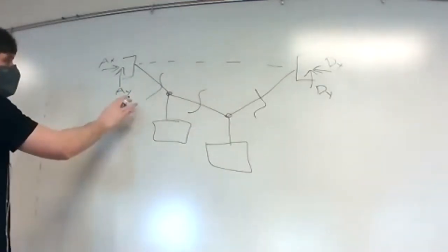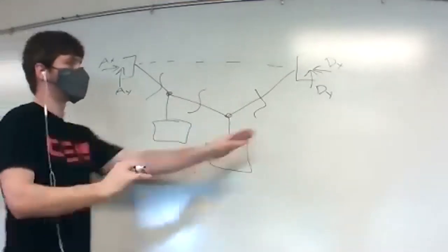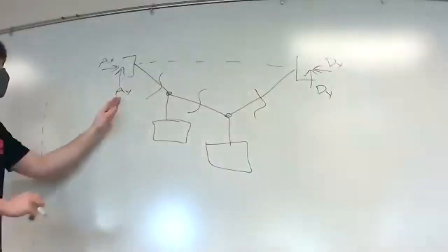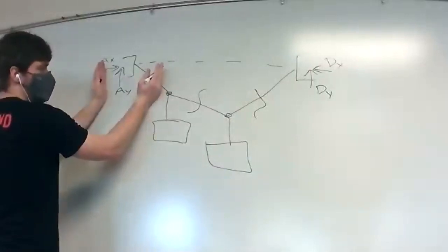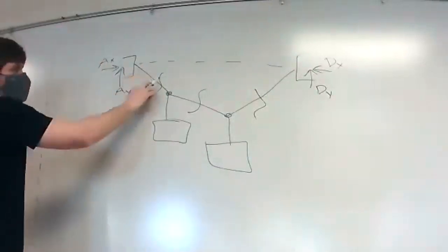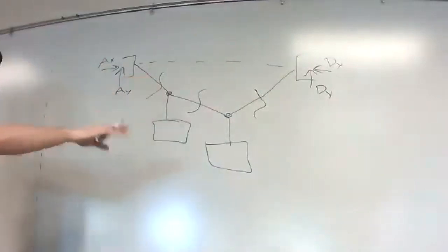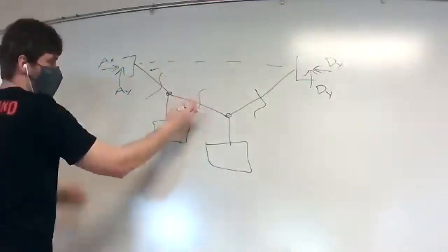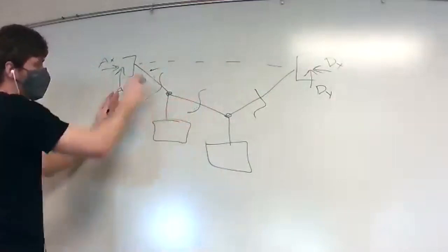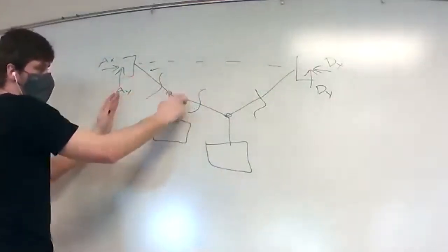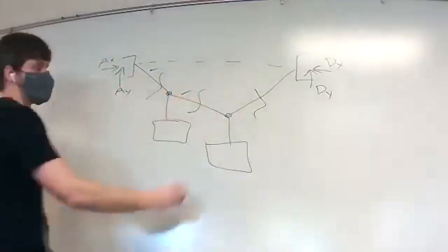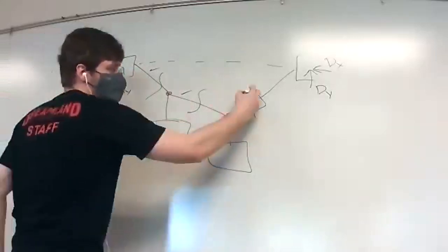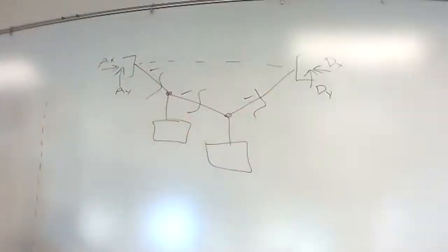So let's say we took the moment at D, we find AY. So AY is considered known at this point. We would sum the forces in the Y direction for this cut. That would be AY and the Y component of this, and that's it. That lets us solve for this. Boom, that tension's known. We take our next cut, go over here, we have this. Sum of forces in Y is going to be AY, the Y component, this weight, and the unknown. Solve for that, boom, we're done. Once again, cut, AY, this tension, weight, this unknown, solve for it, boom, we're done.